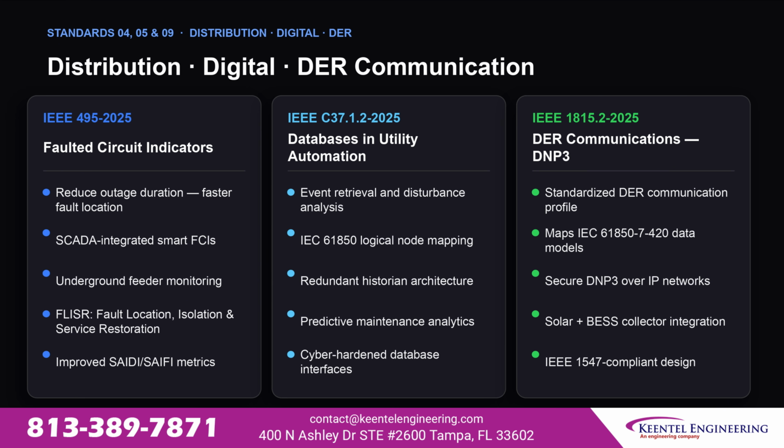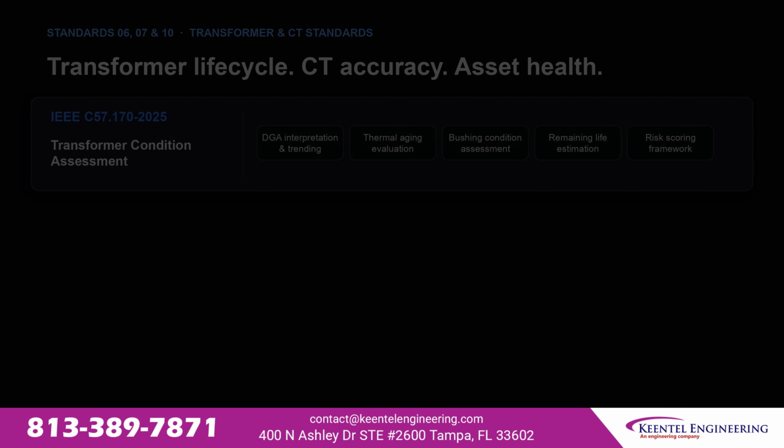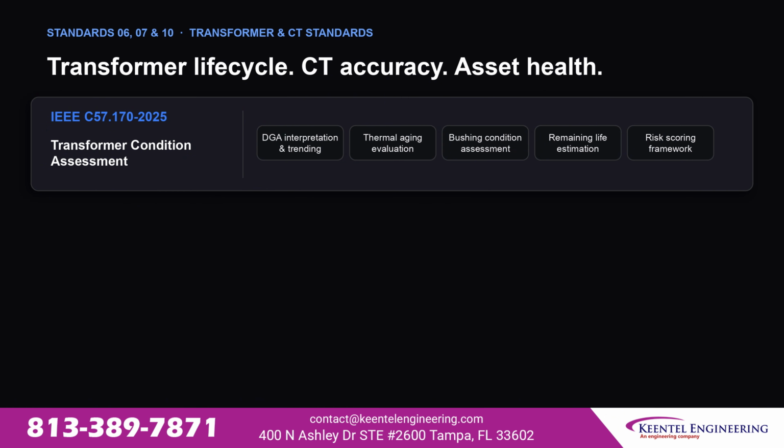IEEE 1815.2-2025 standardizes DER communication using DNP3 mapped to IEC 61850-7-420 data models. Solar, wind, and BESS facilities now have a defined, secure, interoperable protocol for utility SCADA integration, which is what makes a modern collector substation actually function. 3 standards focused on asset reliability.